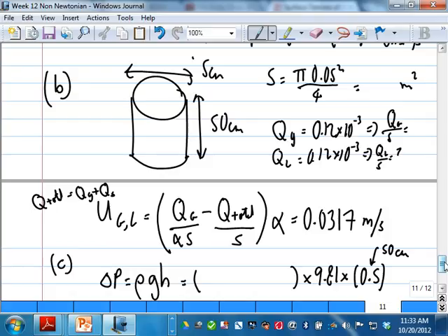So, if you are still confused about this one, basically you look at it, this is the volumetric flow rate divided by the area of the bubble. So this is actually the velocity of the bubble. Alright? This is the average velocity of the whole system. So this QGL is basically the velocity of the bubble minus the average velocity of the system. So it's the drift velocity, how fast the bubbles are drifting, how much faster the bubbles are relative to the average flow.